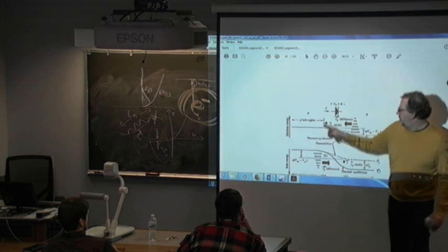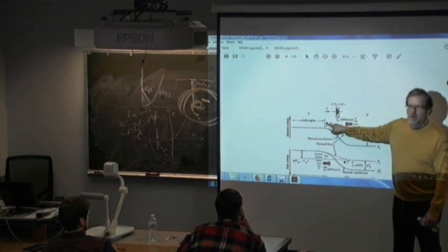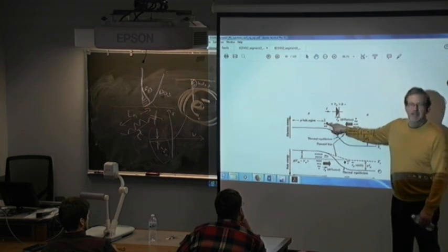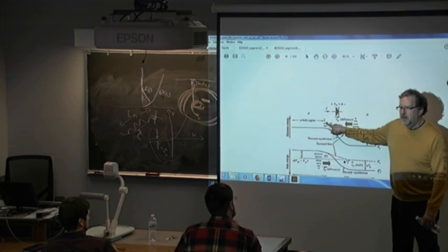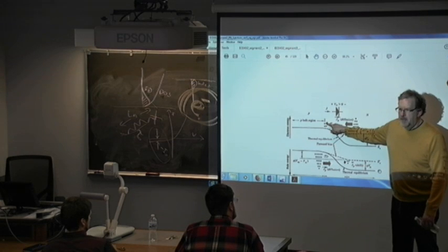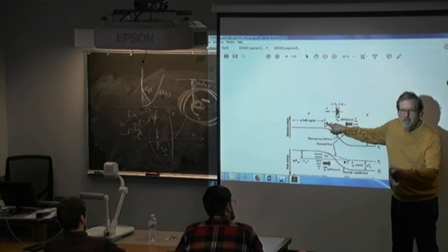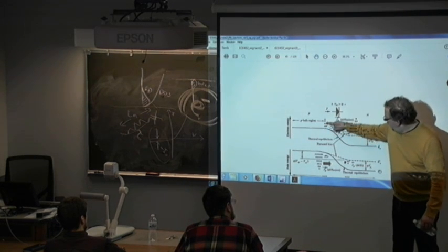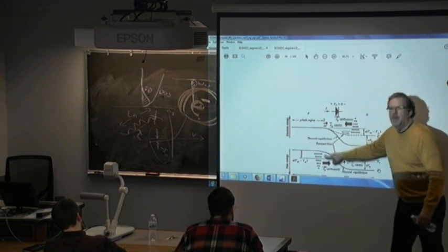His question is, where does this electron go when it recombines? Doesn't it become part of the... It's recombined with the holes in the valence band? Yeah, it's just going to fall down, and we have all these majority carrier holes here, so it just recombines.